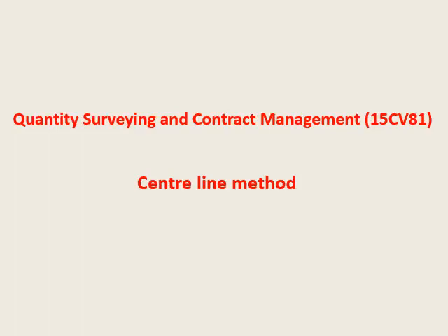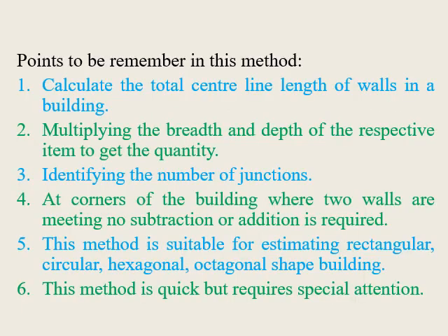So let us discuss the centerline method for estimation of a building. Before finding the quantities of various items of a building such as earthwork excavation, earthwork infilling, foundation bed concrete, size stone masonry, plinth concrete, etc., we should keep some points in mind. Number one, calculate the total center line of the wall in a building.